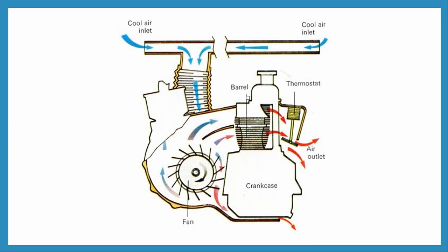As it enters the engine combustion chamber, and after the power is generated, heat is produced. That heat passes through these fins. These horizontal lines are showing the fins or ribs which are fitted on the cylinder, on the engine body.